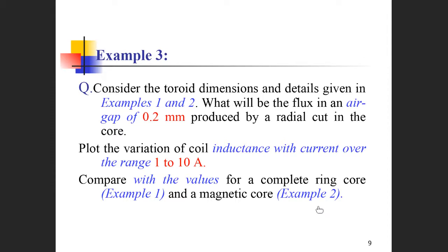That will be different. In example 1, you got the air-cored coil that has a very small inductance, about 0.83 millihenries. In example 2, you just change the core material into cast steel, then you got 78.9 millihenries. That is a big difference. The difference comes from the permeabilities.